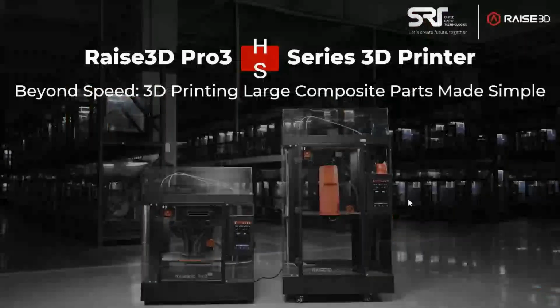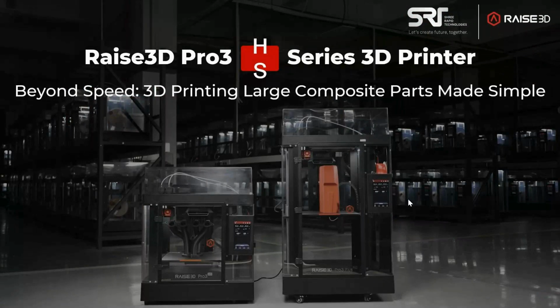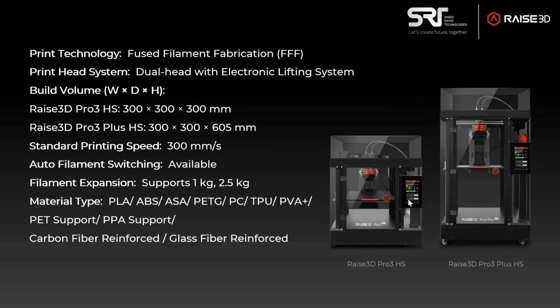And the printer compatible to run these hypercore filaments is the Raise3D Pro 3 HS series. So you have Pro 3 HS and Pro 3 Plus HS. Pro 3 HS has a build volume of 300 mm cubed. Pro 3 Plus HS has 300 by 605 mm, where you can achieve printing speeds of up to 300 mm per second. It has automatic filament switching, and compatible materials range from general PLA, ABS to industrial composites, as well as hyperspeed and hypercore filaments.